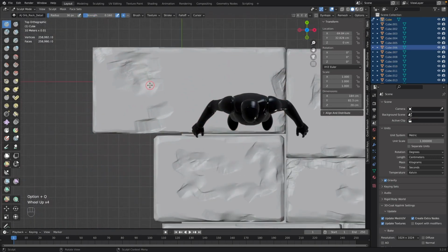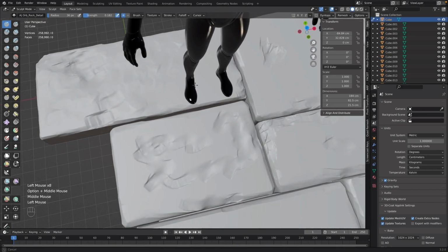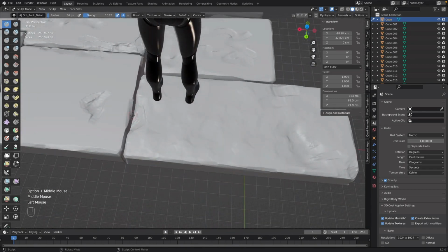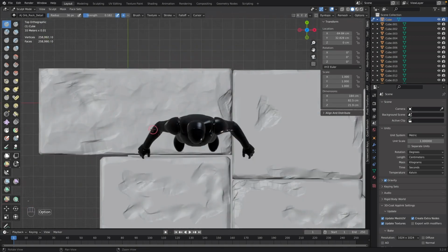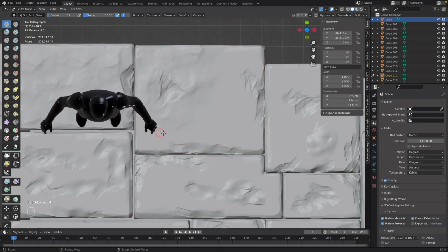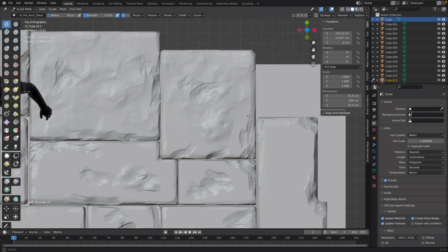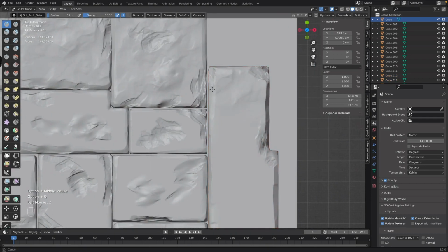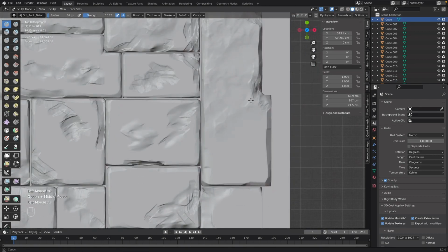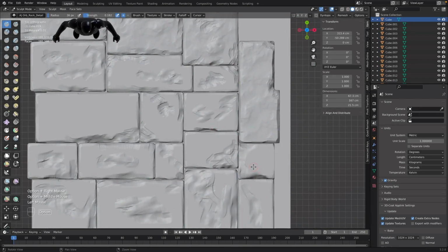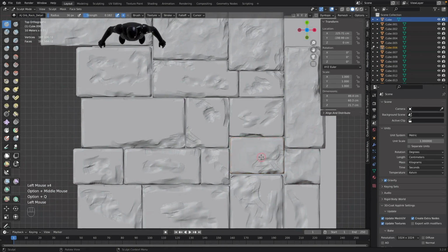Now I just switched to a stencil brush called Orb Rock Detail to add some textures on top of our bricks. This will create some nice details for our normal map, and it will help with creating some variation on our non-even surfaces. Just click and drag on top of the surface with your mouse. You can just put the mannequin on top of your bricks and see if the stencils are too big or too small. And that way you can create a better texture.